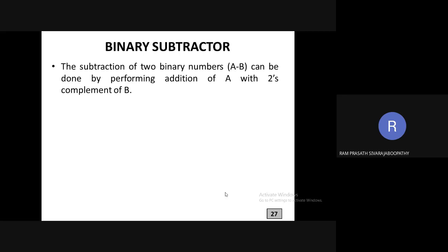See, what I am asking is, is it possible to perform subtraction in terms of addition? The answer is shown in the slide itself. Yes. The same circuit, with a little modification, will work as a binary subtractor. Using 2's complement addition, we are going to perform it. Now, A minus B is equal to what? A plus 2's complement of B. Correct? A minus B using 2's complement addition.